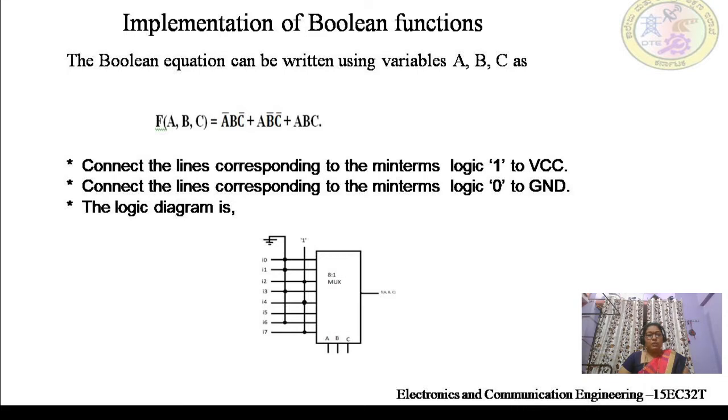Now the input lines are connected such that if the minterm is present, the input line corresponding to that minterm is connected to logic 1. If the minterm is absent in the logic expression, then the corresponding input line is connected to logic 0 or ground. In this example, minterms 2, 4 and 7 are present.